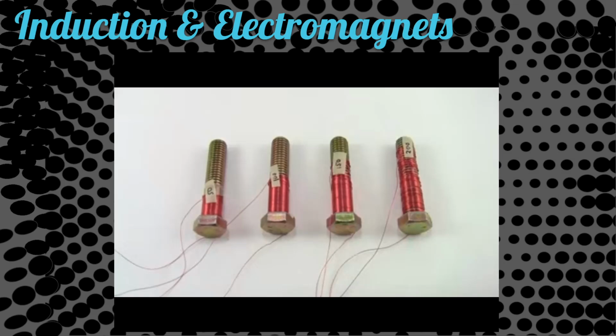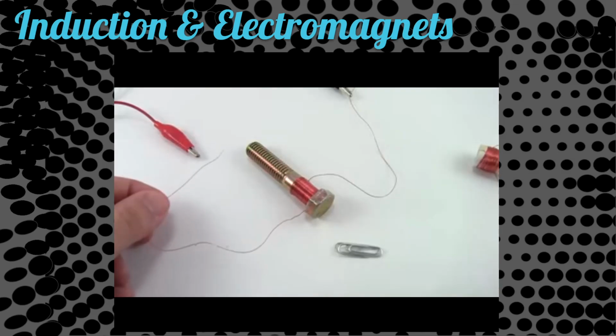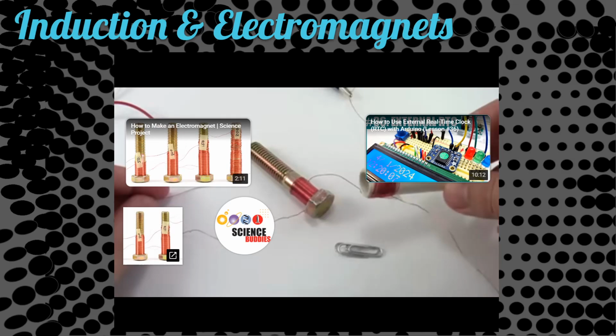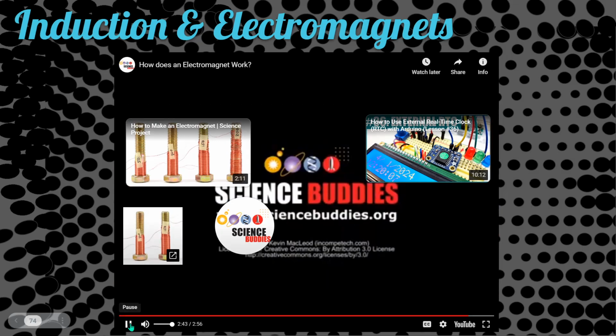To change the strength of an electromagnet, you can change the number of turns in the coil, the length of the coil, the amount of current flowing through the coil, or the core material, all of which would make a great science project. Because they have very low resistance, the wires in electromagnets can get very hot, so you should always disconnect them when not in use. The paper electromagnet in this video was just for a demonstration, but you should not try this at home because the paper could actually catch on fire. To see a variety of science.